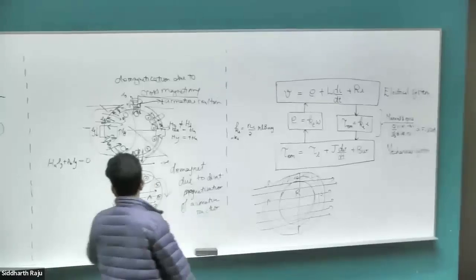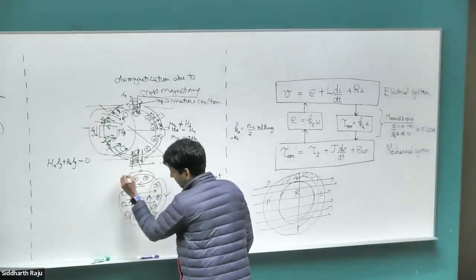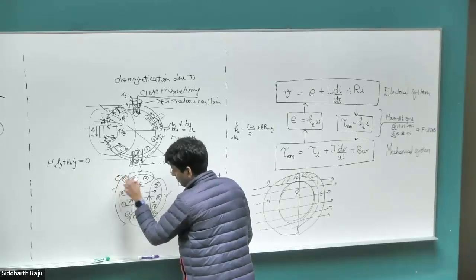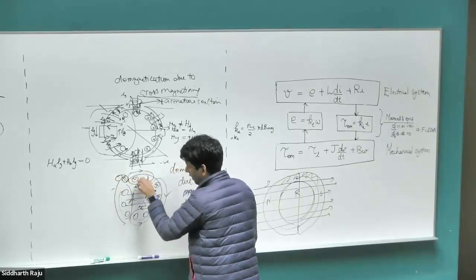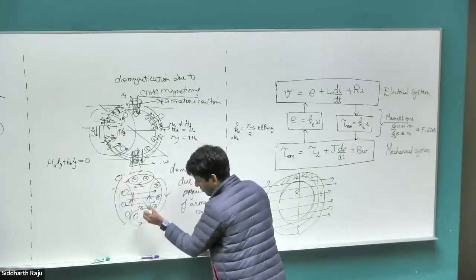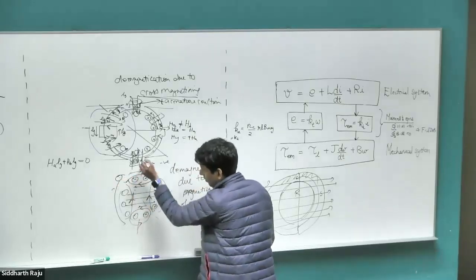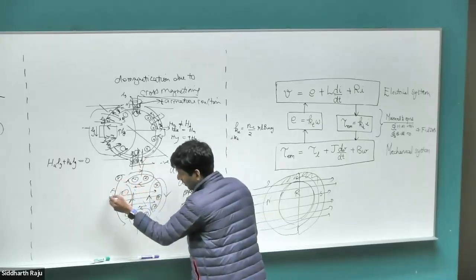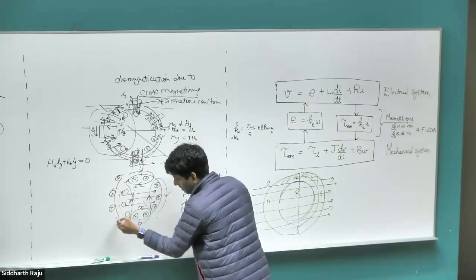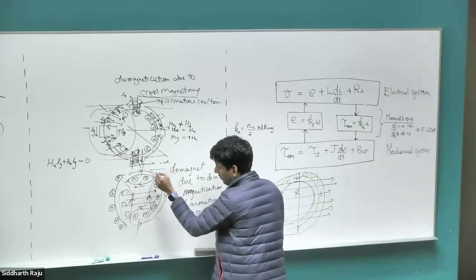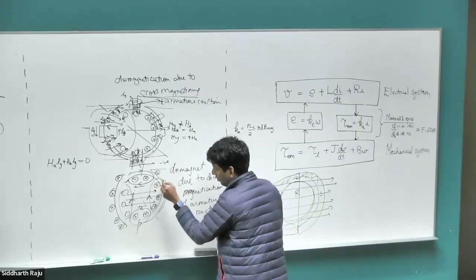where we have these conductors and we have this pole face. So this was the case when we had our shifted neutral axis. For high power motors, you won't shift it at all. You'll definitely want to put it right in the center. And then we basically have conductors on the stator core, which exactly cancel out whatever the field lines are created by the conductors on the rotor.